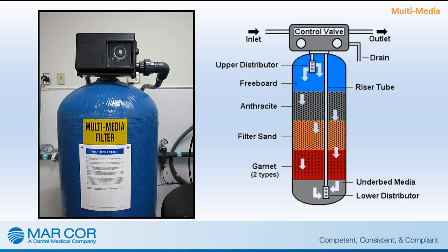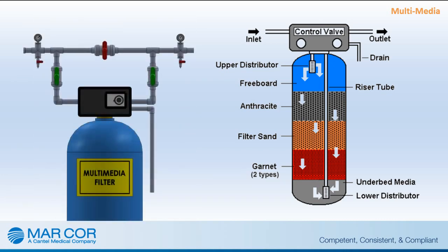Water in the multimedia filter tank is filtered through multiple layers of various sized gravel, sand, and anthracite, which is a specific variety of coal. The multimedia filter will automatically be backwashed to rinse out collected particulates, so timers need to be checked. If the filter goes into backwash during times of patient treatments, the RO will be locked out and shut down. Recording pre- and post-filter pressures may be part of your